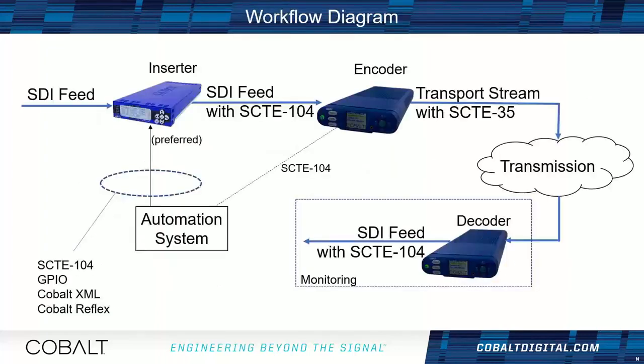We support all of that. We have our inserters taking an SDI, get signaled by an automation system, and then gets an SDI feed with SCTE 104. Our inserters can be signaled by using SCTE 104 itself, by GPIO, or by some proprietary Cobalt protocols. All of that is available.